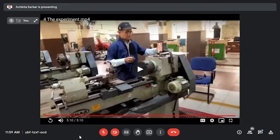Now this surface gauge has a scriber, a bent or offset type scriber. We need to adjust the height of the point of the marking block or surface gauge. Where the point is touching, we have to check the opposite side. If there is a gap, then we have to move the job downward by adjusting the four jaws. This is basically required to locate the center of the workpiece, whether it is matching with the chuck center or not.